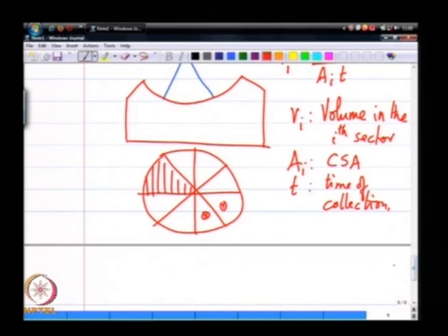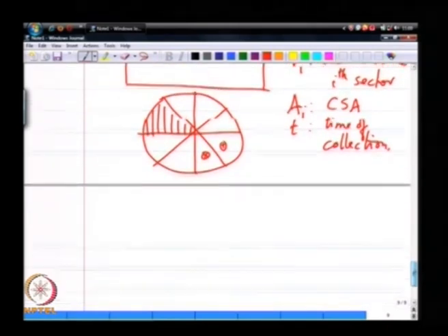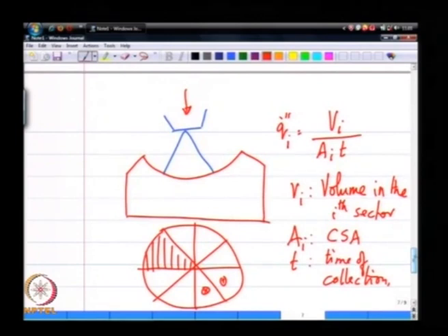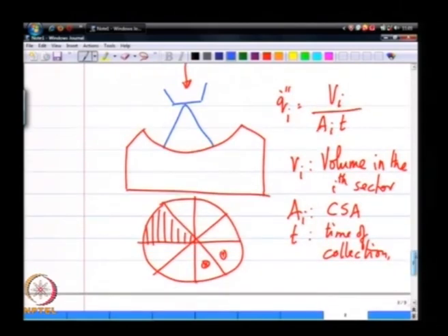Okay. So, these are all mechanical or intrusive methods of measurement. I take this device, stick it underneath a spray, and from knowing the volume collected in each of these 8 sectors, which then drain into separate measuring tubes, and by knowing the volume collected in each of the separate tubes, I am able to estimate the degree of non uniformity in the spray.